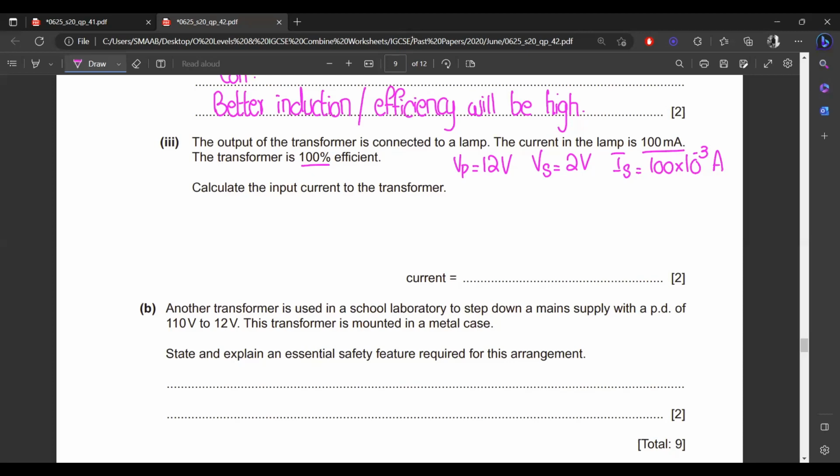You just need to compare the power on both sides, that input power is equal to the output power, or we can compare the voltage with the reference. It depends upon the question. Most of the time they ask about number of turns, so we use the formula of number of turns. But if they are asking with the reference of voltage and current, so we know that in the formula of power, there is a reference of value of voltage and current.